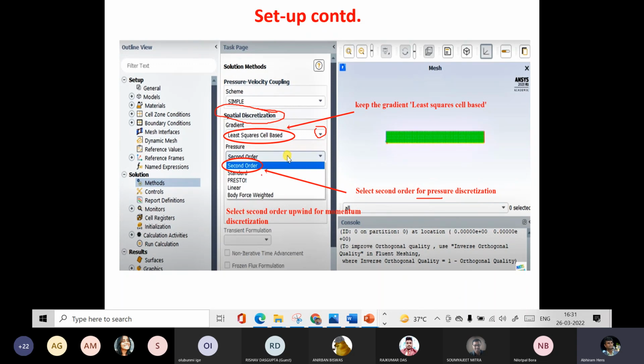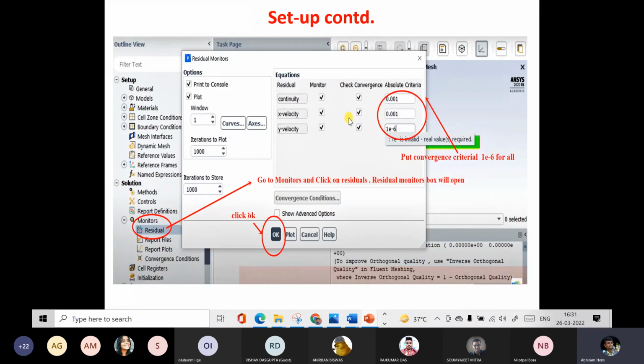So you see that it is step by step. First it is gradient, this is declared, then the pressure term is declared, then after that for the momentum equation you can take this second order upwind scheme. So these are different schemes. Second order upwind scheme is a very common scheme. Similarly, a lot of other schemes are available, you choose any one. Again, perfect selection of the scheme will come with experience, so you need to select something here.